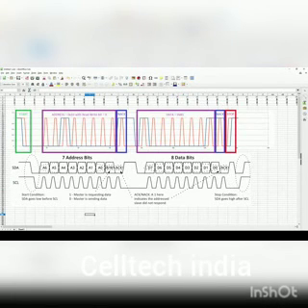Okay, so I've got a scatterplot in LibreCalc here, and let's just check it. Here's the start condition, and here we have the address. There are 7 bits there, and here's the acknowledgement, which we haven't received because we're not actually talking to a device. And the condition before the data byte is correct, so it seems like our formation of the frame is correct.